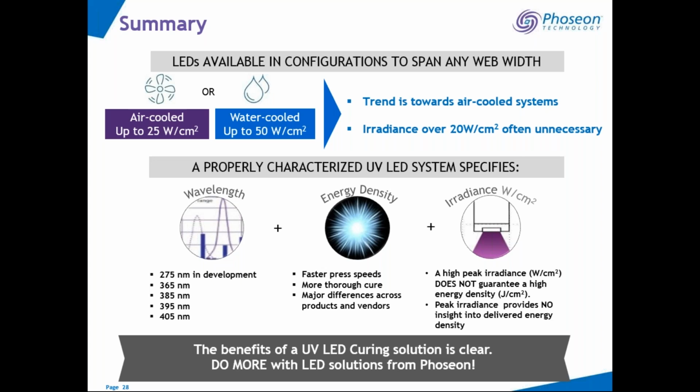Basically, the UVC is giving us a little bit broader availability of the photo initiator packages. And so we see the UVC coming in down the road to help maybe reduce ink costs at some point. But that's, I think, in the future a little bit as the UVC develops. And then we will have to take into account those other concerns with UVC as far as shielding it properly to make sure that you don't have any visible light or the UVC light coming out, as well as the ozone extraction. So we're not there yet. UVA is still a great solution today, but we're keeping our options open for future technology developments.